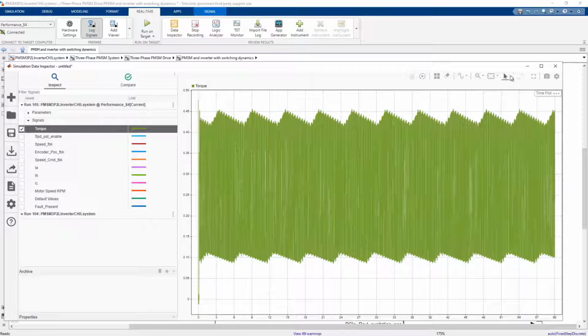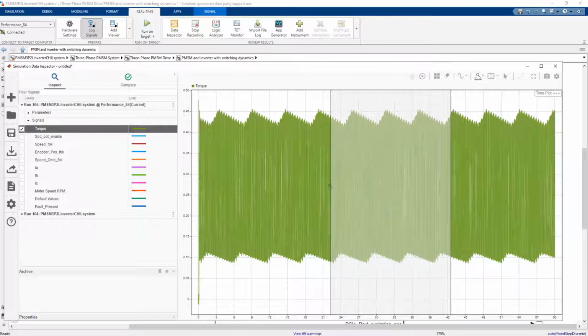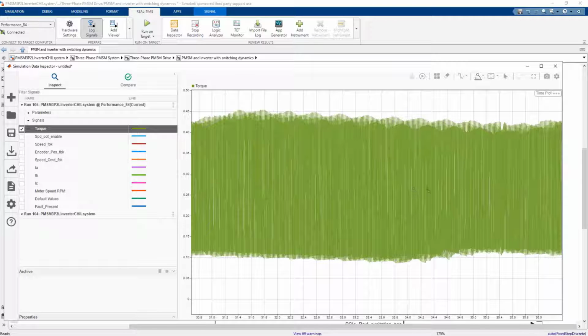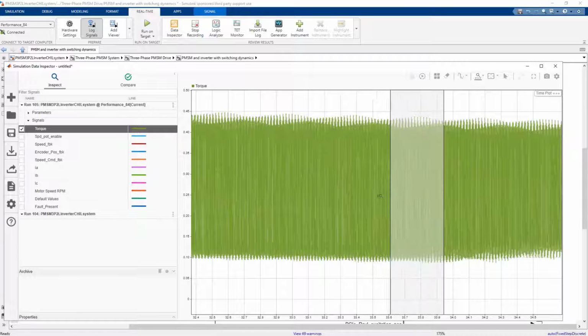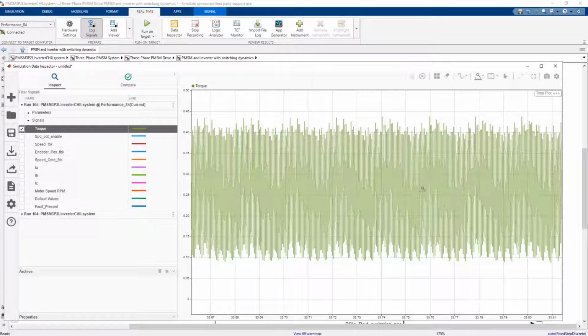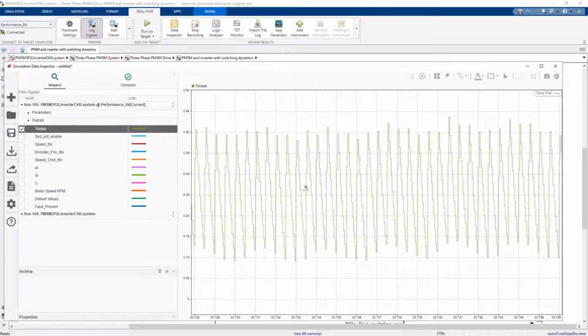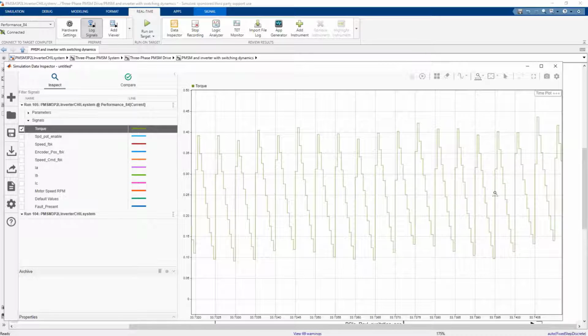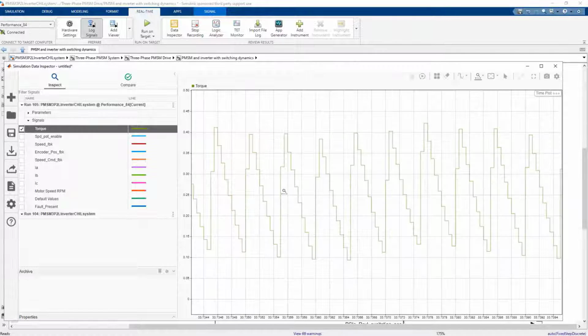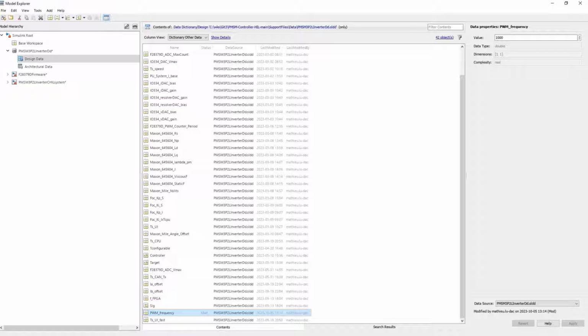Torque ripples are a source of instability for the control, but even if your algorithm can deal with them, they might introduce vibration in the system, leading to noise or even premature mechanical failures. There are many ways to tackle such torque ripples during motor control development. We can try to use a different motor, for instance with a higher electrical time constant. Another approach is to have a less stiff current controller. Here, we will simply increase the PWM period.